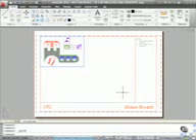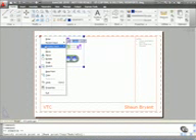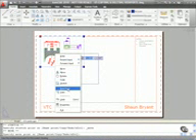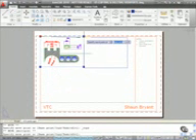Copying and deleting viewports is very easy as well. The copying exercise is very similar to moving a viewport. So if I click on this viewport here, I get my 4 grips again. What I can do there is click on a grip, let's say this top left one, right click, move, right click, copy, and now I can copy to my heart's content.